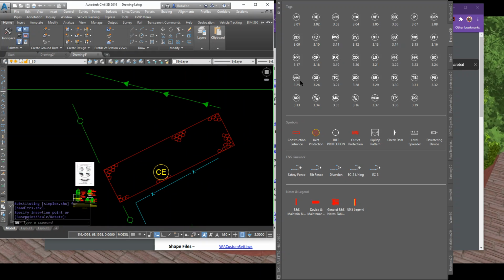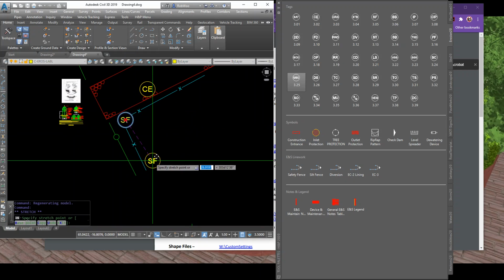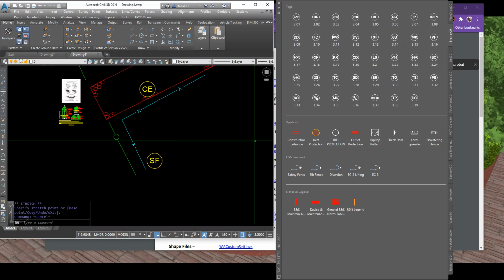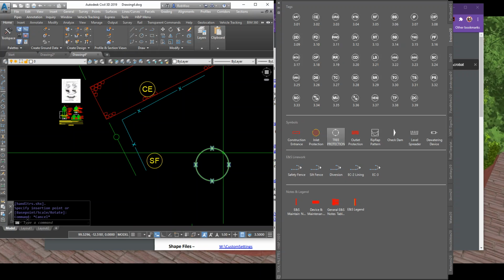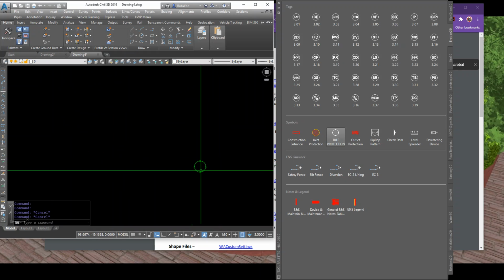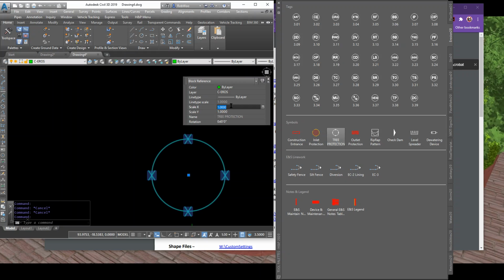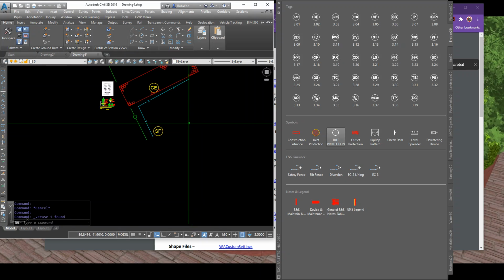Again, these symbols will wipe out anything behind them, so you can insert those into the drawing and see how the line work will not cover up the label or the symbol itself. So you see I've inserted this at 20 scale. One thing that's nice about this is the X's don't disappear based on the line type. You can put those in at any scale that you want.